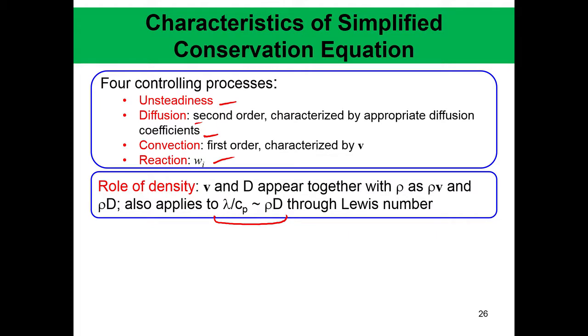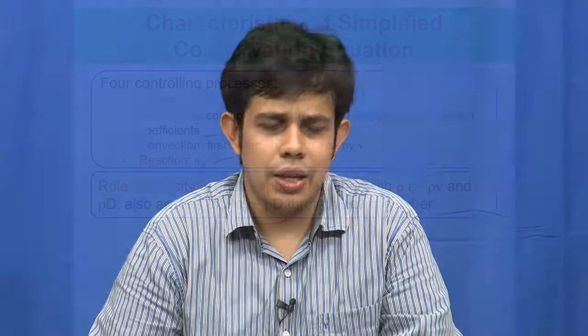For example, in a gas turbine engine, combustion happens at a Mach number of about 0.1, 0.2, something like that. And the pressure inside a gas turbine combustor is very high, 30 bar, but the pressure does not change much. The pressure change is very small compared to how it changes through the compressor and through the turbine. But temperature changes by a huge amount, and because temperature changes, the density changes. So we can assume it's like an isobaric flow. Of course, it is not actually isobaric.